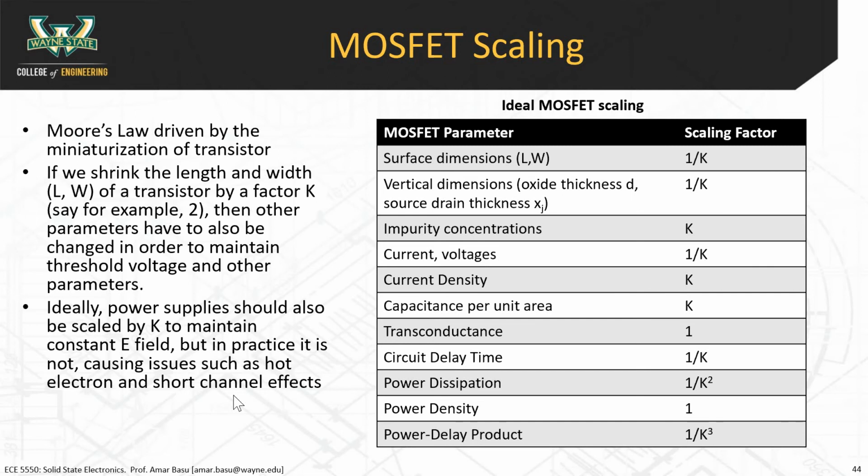5 millivolts. It would be very difficult to control transistors if your threshold voltages were 5 millivolts. Because 5 millivolts is like, if you put an electrode on your skin, you can get 5 millivolts of signal out of it. It'd be very difficult to control the on-off state of the transistors. So we've only gone from like 5 volts of threshold and power supply voltages down to maybe like 1 volt, and less than 1 volt in some cases. We can't go down much further than that because noise could cause the transistors to go on and off. So we haven't done the ideal scaling.